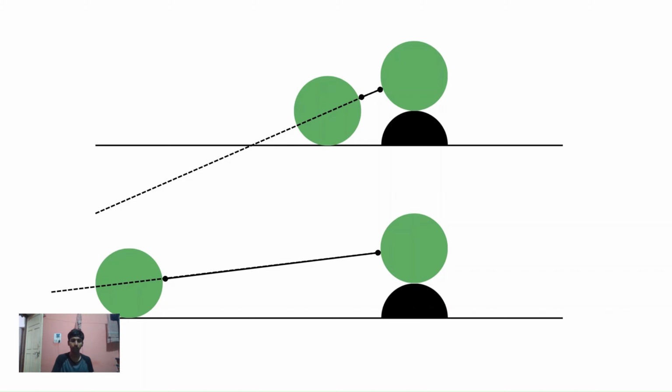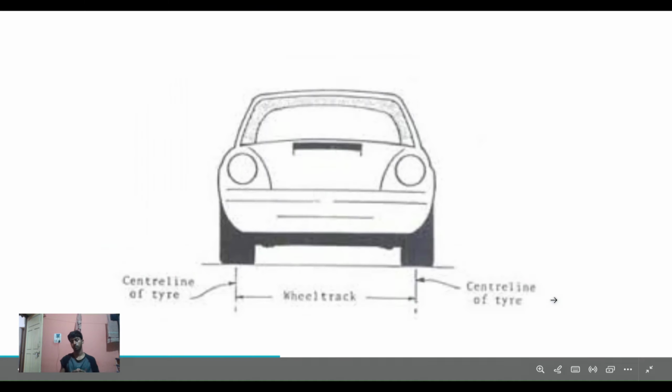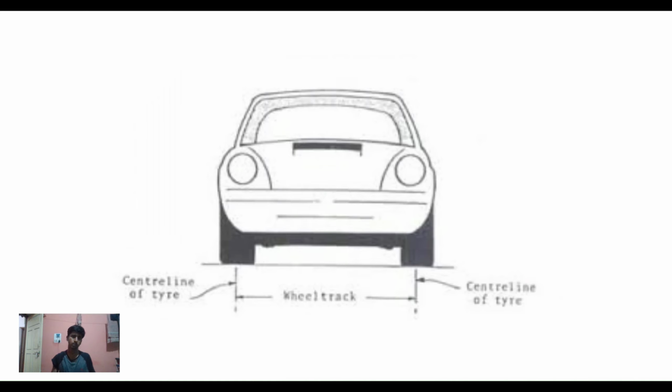If you make it too big, then when you're doing tight turns, it will definitely cause more problems. So choose an optimum value which is just able to satisfy all the parameters I just said, along with some clearance value or additional value, which makes the rider feel a bit more comfortable with the space available to him. Okay, so that was about the wheelbase.